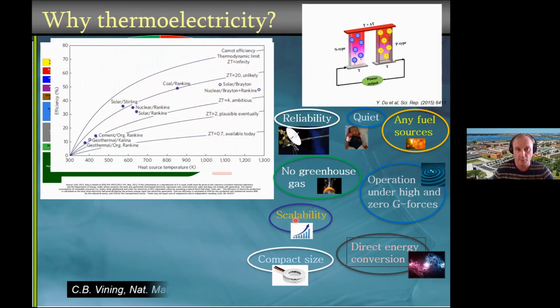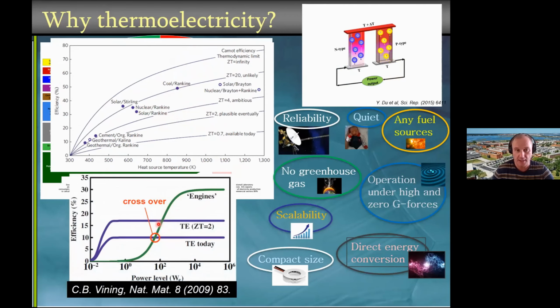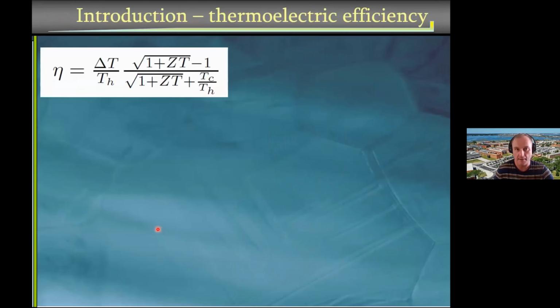So the story is very fine, but unfortunately, if we are speaking about efficiency, we are somewhere here. And if you compare thermoelectrics to alternative technologies, like thermodynamic engines, Rankine or Stirling cycles, they're pretty far above thermoelectrics, and even with very optimistic expectations, I think we cannot come to this level. Still, the size favors thermoelectric applications, and when I was speaking about applications which require relatively low or intermediate power levels, we can consider thermoelectric technology competitive.